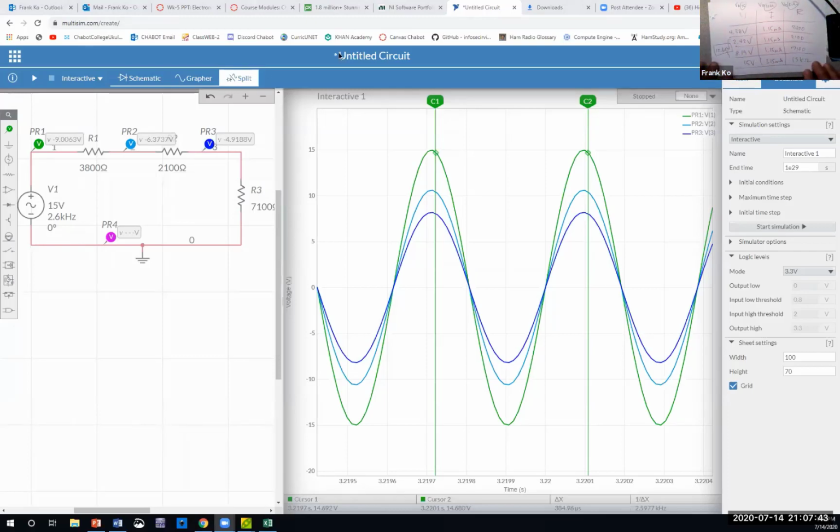Okay. Can everybody see my VIR chart? My VIR chart should look like your VIR chart, or your VIR chart should look like mine. You have your resistances, total, current. You double check the ohms total, you double check the current total, then you fill in the current column. After you fill in the current column, you multiply, and you end up with these voltages. So are we happy with these voltages so far? Yeah. Done. Now, we want voltages at specific points with respect to ground.